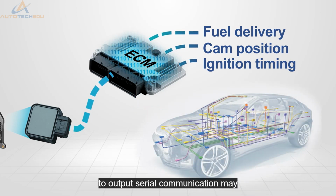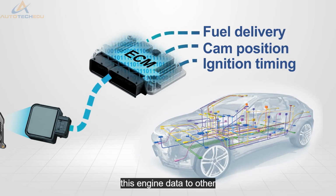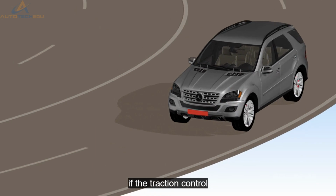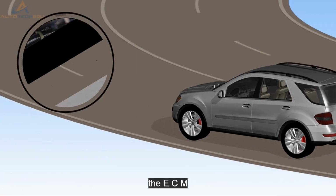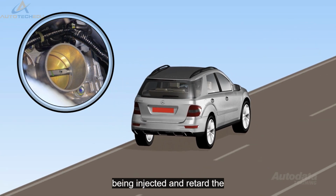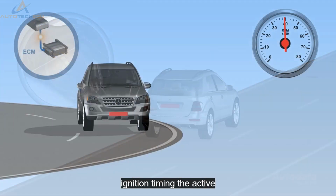Serial communication may then be used to relay this engine data to other control modules within the network. If the traction control module detects wheel spin, the ECM will relax the throttle valve angle, reduce the amount of fuel being injected, and retard the ignition timing.